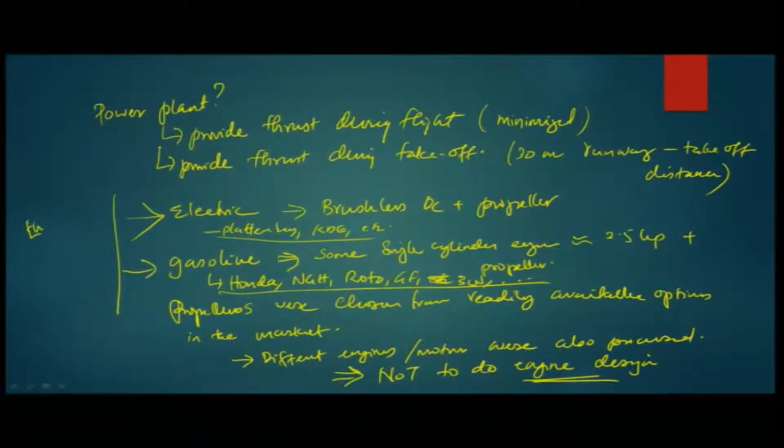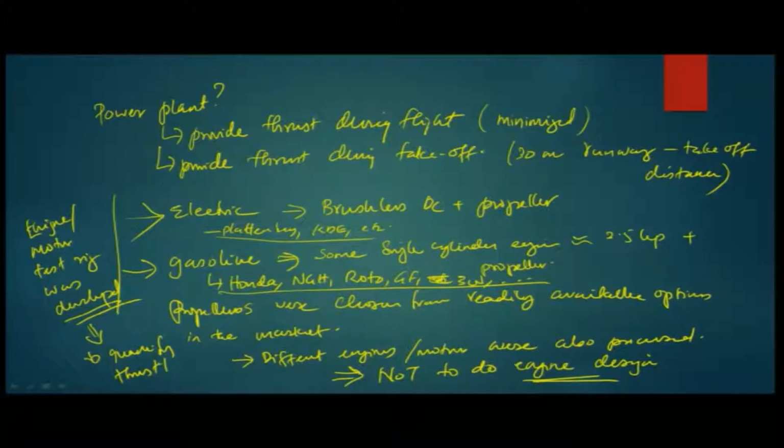So, an engine/motor test rig was developed. To do what? To quantify thrust. Adding different motor-propeller or engine-propeller combinations, we need to quantify how much thrust each would give.